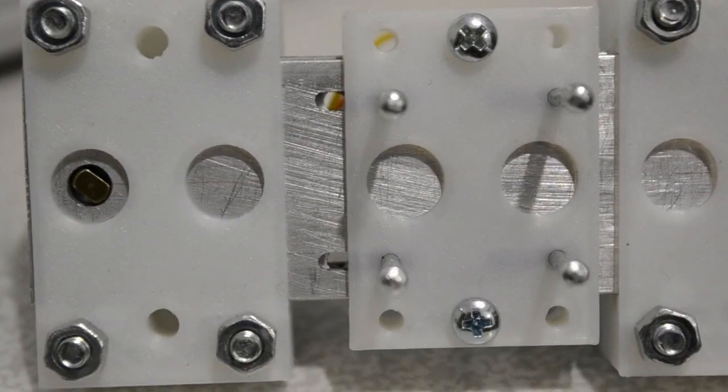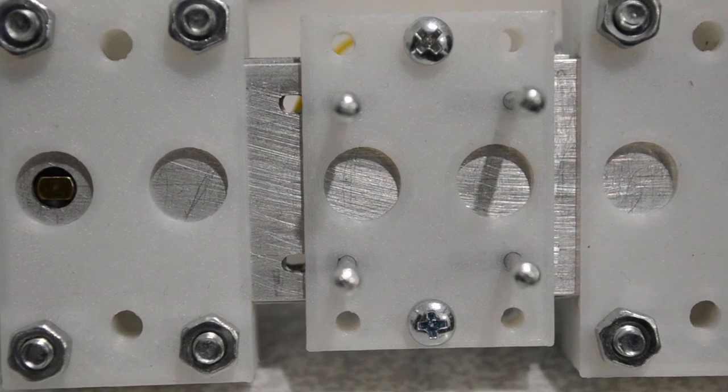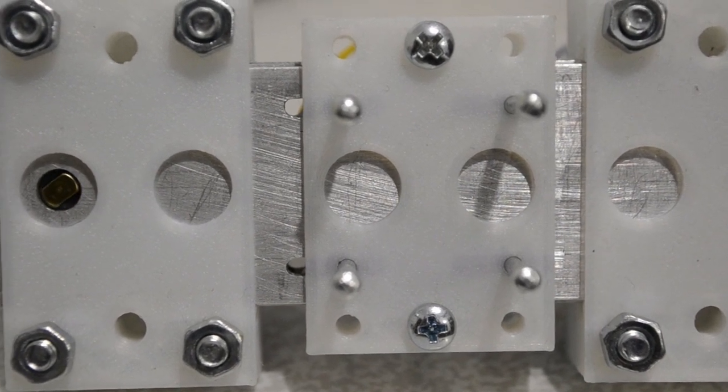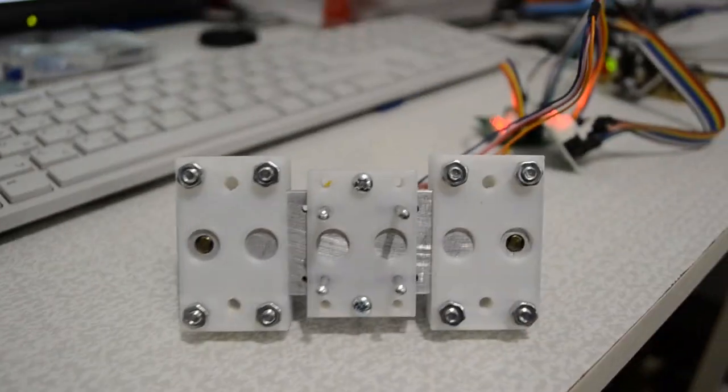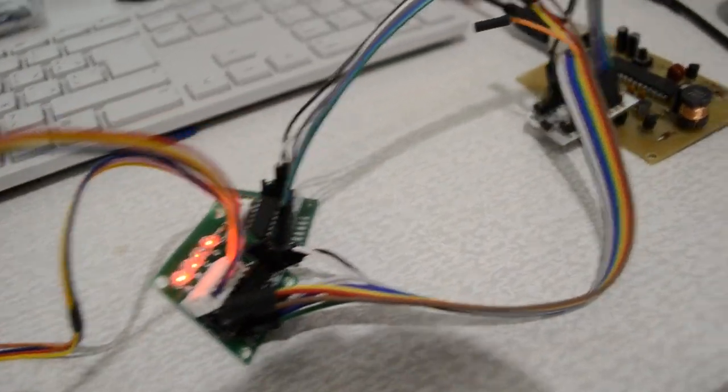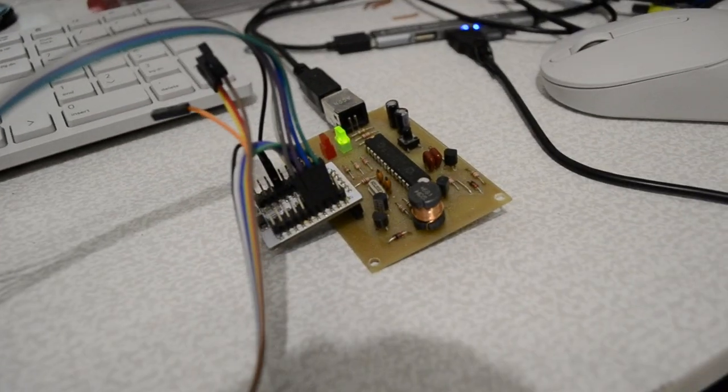In total, one full rotation gives us 2π, or 6.28 mm of travel, or in other words, 10 mm of useful travel corresponds to 1.59 revolutions.